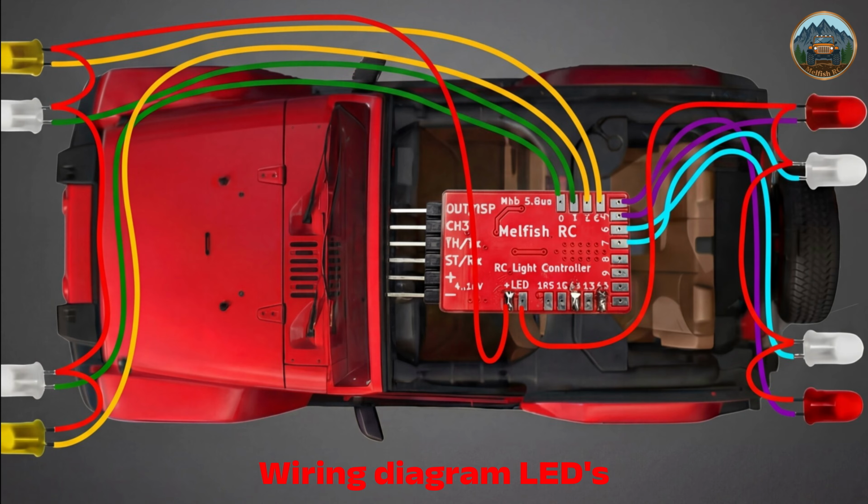Solder these in series. For example, your main two front lights on channel 0 and 1. Repeat this process for the rest of the lights. If you want to keep more channels available for other lights, you can choose to solder the main two front lights to one channel instead of using two.